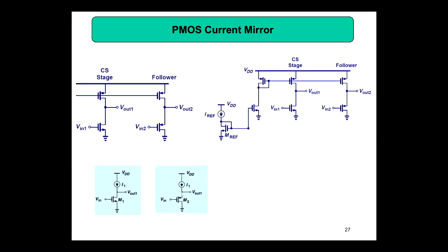And when you are designing a chip, what you will find is you will have so many PMOS and so many NMOS current mirrors, because you may have these types of current sources. See, this is pretty common in chip design, because this is an amplifier and then your load resistor is replaced with a current source. Then this is a follower circuit, a buffer circuit. Here also PNP, and the load is replaced with a current source. In order to replace this current source with a transistor, you definitely need a PMOS. Here definitely you need a PMOS.